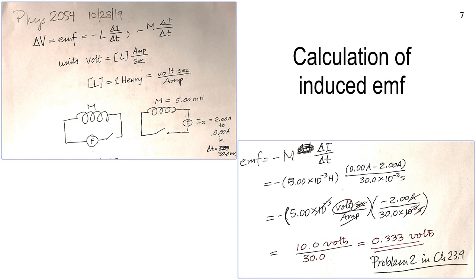All right. Now I'm going to convert the henries. I didn't do it in my scratch paper, but I'm going to do it here. I'm going to keep the same numbers here, times 10 to the minus 3. And instead of a capital H for Henry, I'm going to change it to volts seconds per ampere, because I'm going to start canceling.